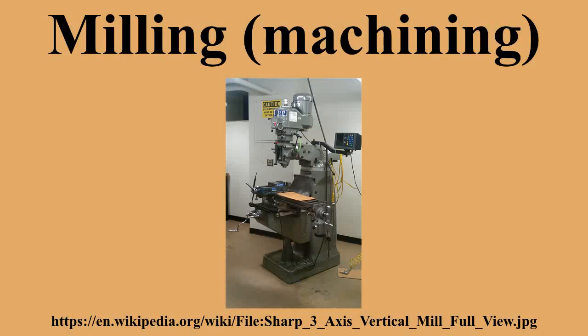Mill orientation. Vertical mill. In the vertical mill, the spindle axis is vertically oriented. Milling cutters are held in the spindle and rotate on its axis. The spindle can generally be extended, allowing plunge cuts and drilling. There are two subcategories of vertical mills, the bed mill and the turret mill.